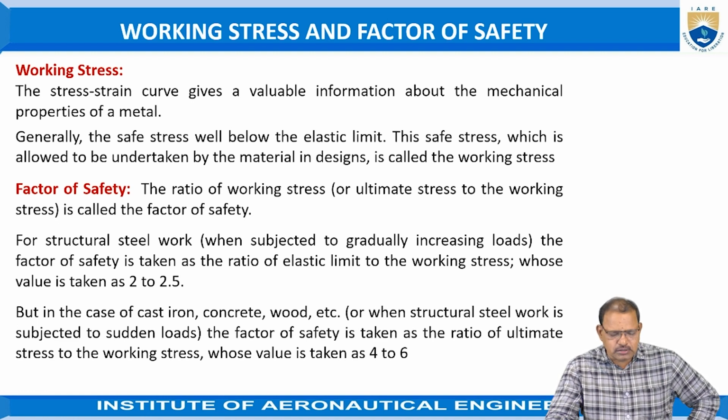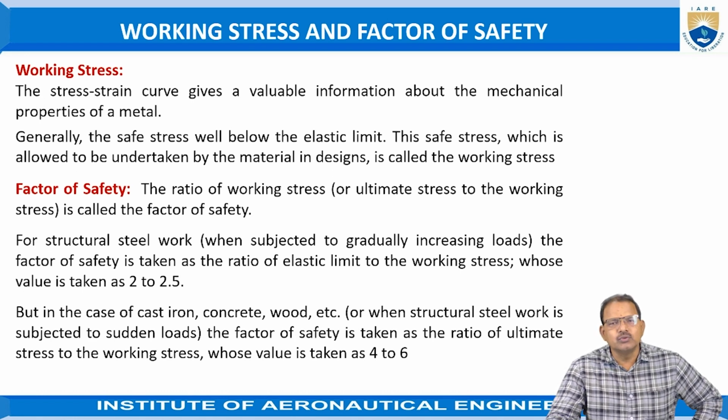For structural steel, the factor of safety is taken as the ratio of elastic limit to the working stress, whose value is taken as 2 to 2.5.